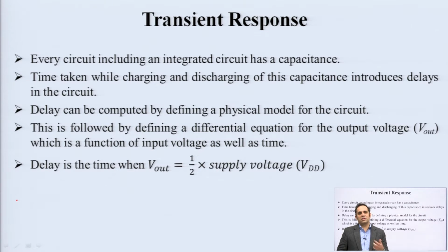So, wherever there is capacitance, there is going to be some amount of charging and discharging which is going to take place. Okay. And the time it takes for this capacitor to charge or for this capacitor to discharge is what produces some amount of a delay inside the circuit. Okay. Even if we talk about digital ICs where we provide some DC input, and when we reverse the polarity of that DC, the output does not switch instantaneously, it takes some amount of finite time.